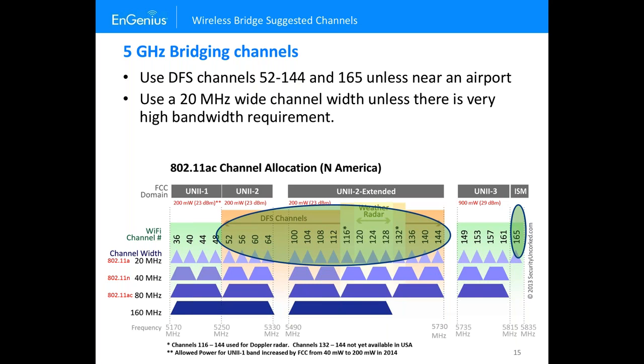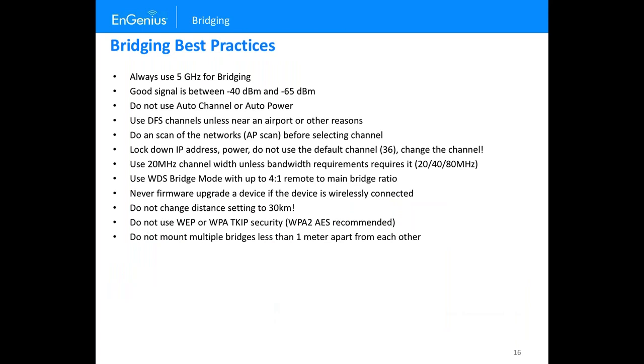In order for a radio to be FCC DFS certified, it has to be 98%. It doesn't say 90% positive or false, just 98% you detect it. So that's the reason why you get false positives, because only 2% is the threshold.